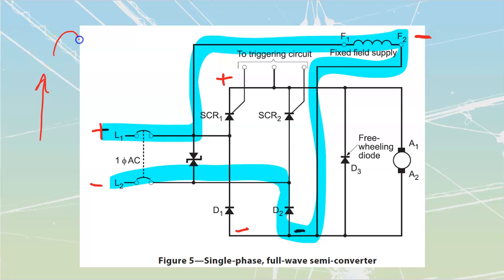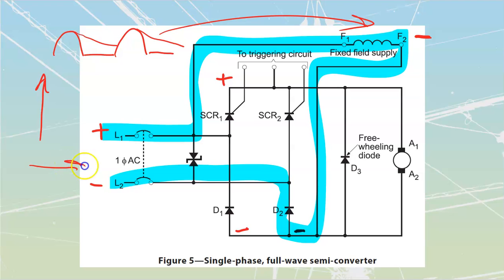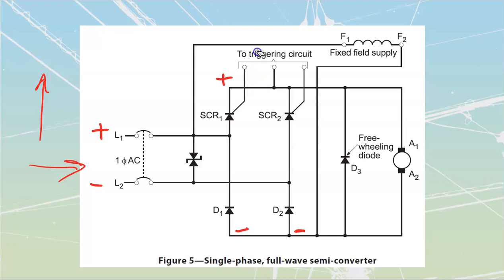It is going to have a half-wave rectified single-phase input, is what this field over here is going to see. Now, because it is an inductor, that means that it is going to smooth out. It's going to drop down by collapsing those lines of flux that it stores around itself back in. This thing is just going to be powered off of those connections there. So it is going to receive constant power as long as there's power feeding into this drive. This thing is going to pick up the positive, negative, and then it's going to block the opposite positive, negative. Okay, that deals with our field.